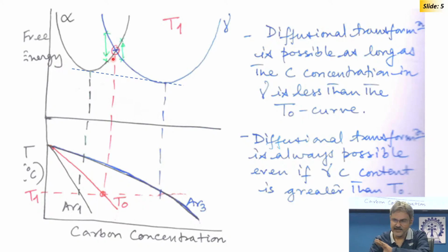transformation. There are two reasons. You have to nucleate. To nucleate, some kind of dislocation reaction is required, as per the Olson and Cohen paper in 1975-76. So, some kind of dislocation dissociation is required. That nucleation requires some amount of energy, plus this kind of transformation is associated with huge strain.